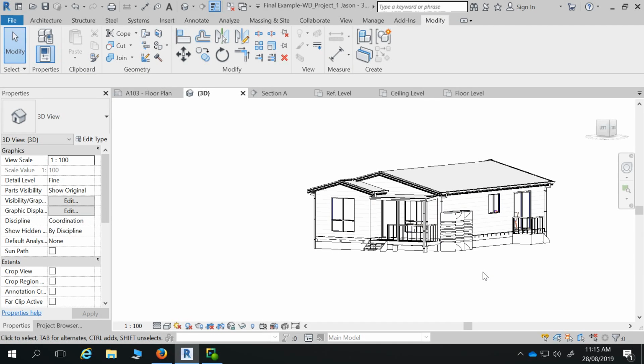So if you're in a bushfire prone area, you'd have to bring it down to the ground because you can't allow embers to get underneath that house. If you're not in a bushfire prone area, you've got the option, just bring it down to past the timber members. And the reason you want to do that is any moisture, rain, is going to drip down, not get pushed into the side of the timber joists, which is going to suck the moisture in and swell and then damage your framing.